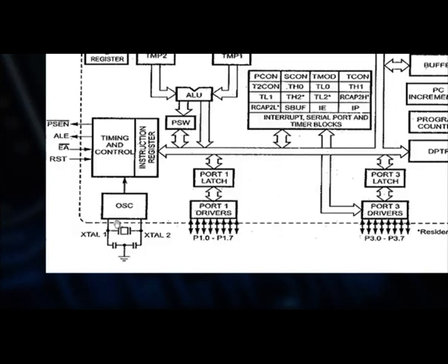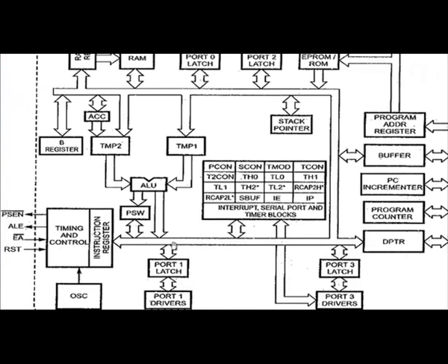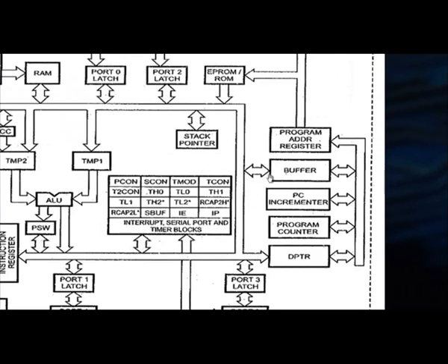Okay. So, there are two 8-bit registers, A and B, and it also has two 16-bit registers. One is the program counter, and another one is the data pointer. The program counter plays a vital role in the 8051 because it is a 16-bit pointer which automatically increases its address by 1 during execution, and is used for fetching and decoding, right. So, it will maintain the sequence of the program execution.